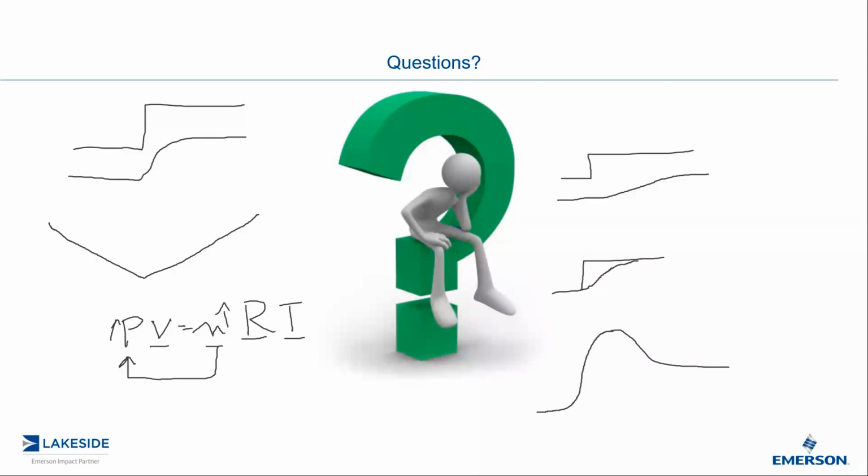That means that if I make step changes all the way across, the process sensitivity will be very different at the bottom end or the top end, at pH 3, 4, and 5, or 8, 9, and 10, than it will be at 7. At 7 it will be very, very sensitive. So obviously your process is changing depending on where you're operating.